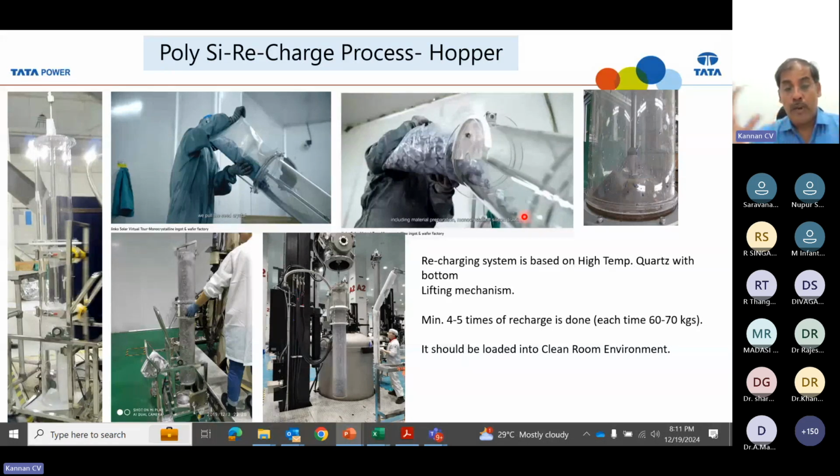Instead of using 5 crucibles for 5 crystals, now it is one crucible, 5 crystals. The crucible is one of the costliest raw materials in the manufacturing process, so you can minimize the overall cost of production. This is the way the industry is working right now. Instead of single crystal growth, they are doing recharging crystal growth.